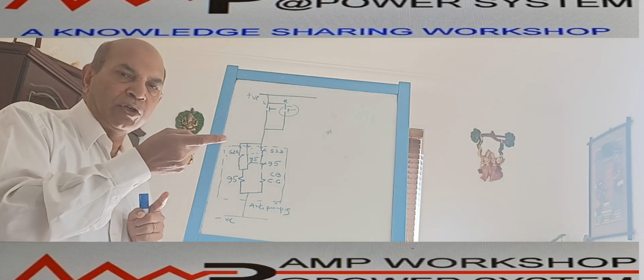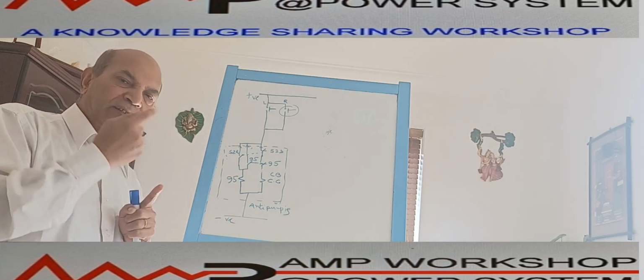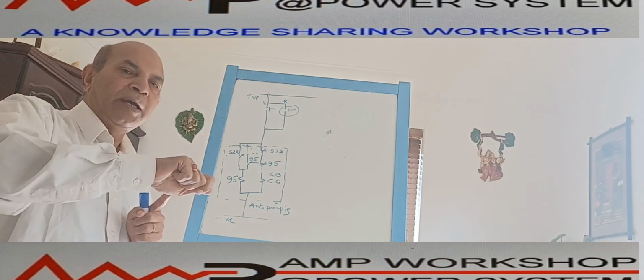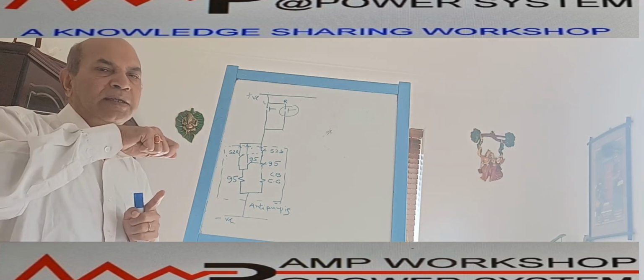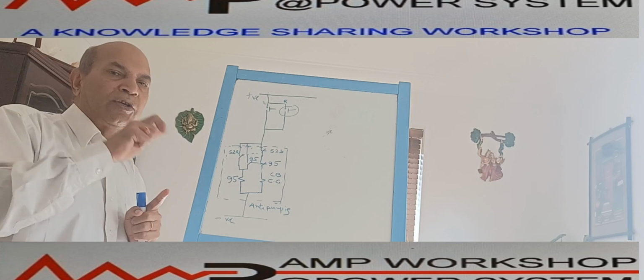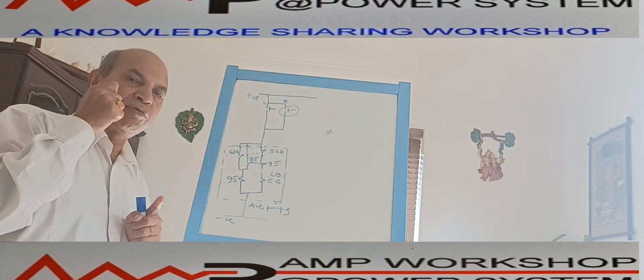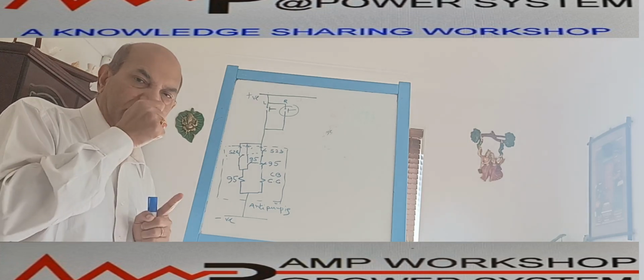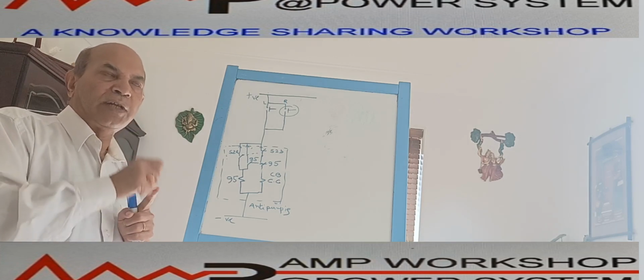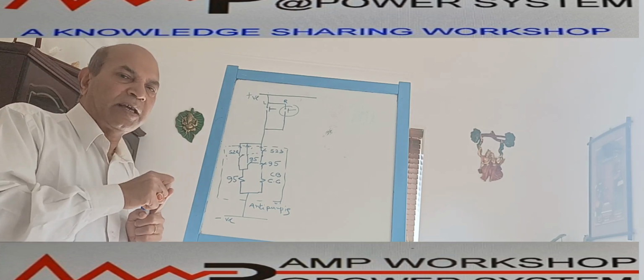Immediately it will get the closing command, then the breaker will trip, but as the system is not synchronized, what will happen? Immediately the breaker will trip due to unsynchronization. Okay, so that is a very wrong operation. In that case, we can put the system at big risk. So we do not do that. That's why there is an arrangement in the circuit breaker itself.